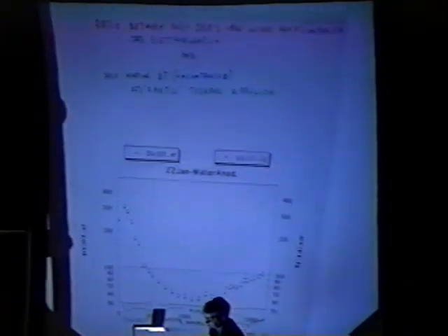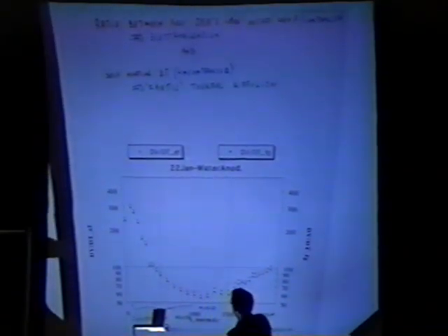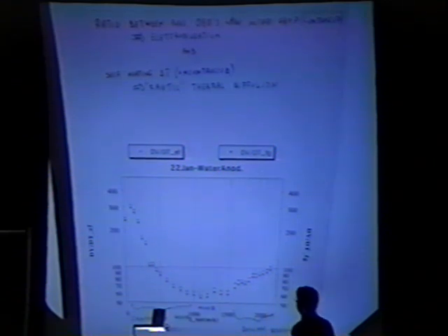This curve is a little bit uncommon, and we try to find some optimal point about how to increase the voltage without increasing the temperature. Because we think the voltage is controlled by electromigration, so we use it for loading and deloading. Temperature is just chaotic for the loading. So we want to maximize this ratio, voltage over temperature.